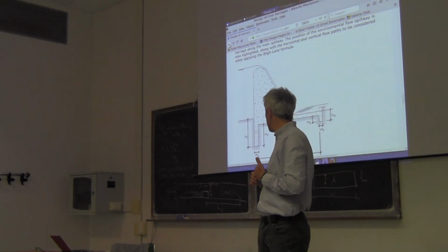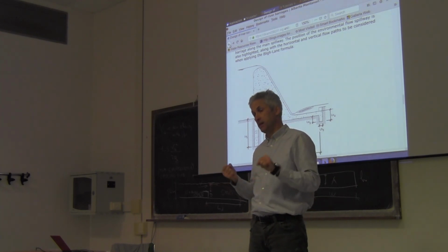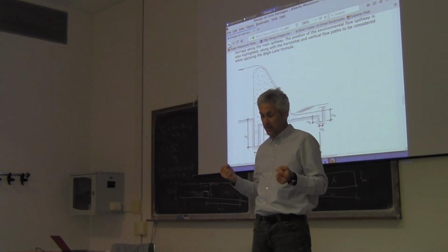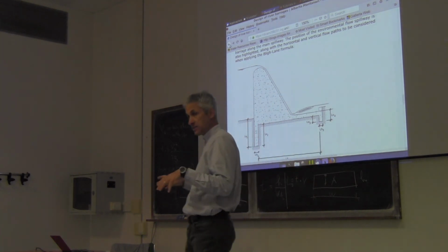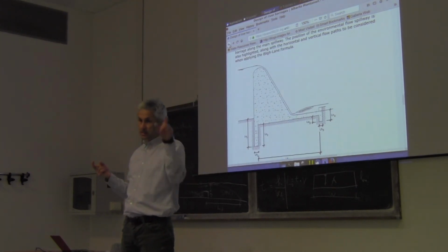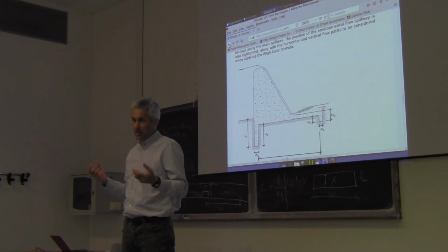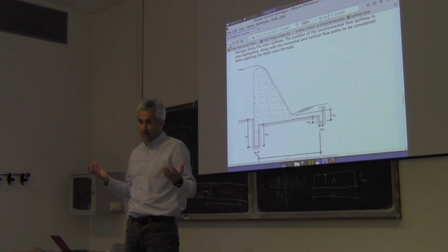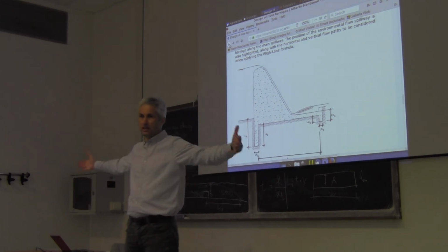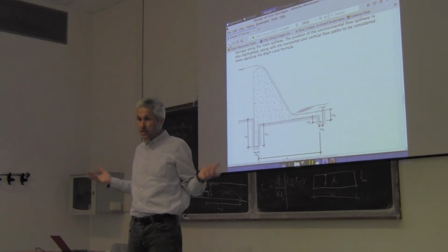The stability of boulders can be increased by connecting boulders with wires, or sometimes we try to stabilize the boulders with concrete, because there is, as I said, this big question mark, because we really don't know what happens during a flood. Sometimes we see boulders as large as houses that are floated by rivers that normally have no water during summer.